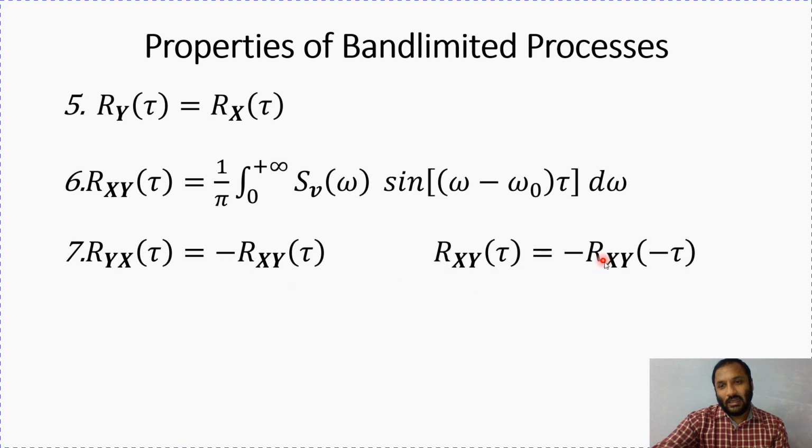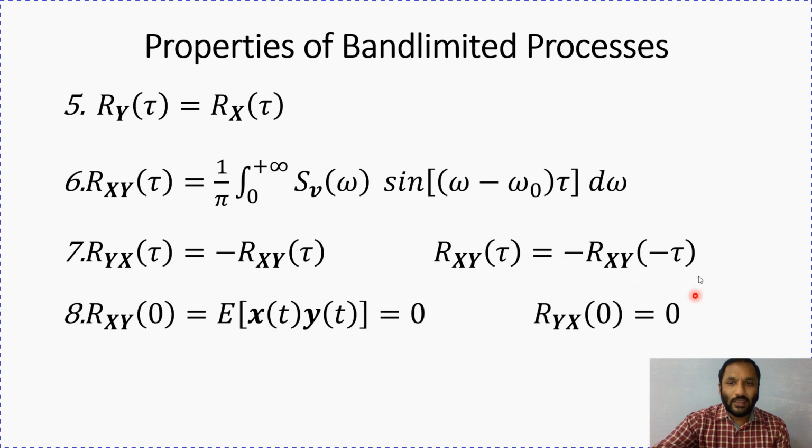That means the reflection of this function should lead us to a negation in the front. So Rxy is an odd function, and also the value of this cross correlation function at delay tau equal to 0 is exactly equal to 0. In other words, by substituting in the above equation, because Ryx will be equal to minus of Rxy, I will have this following result.